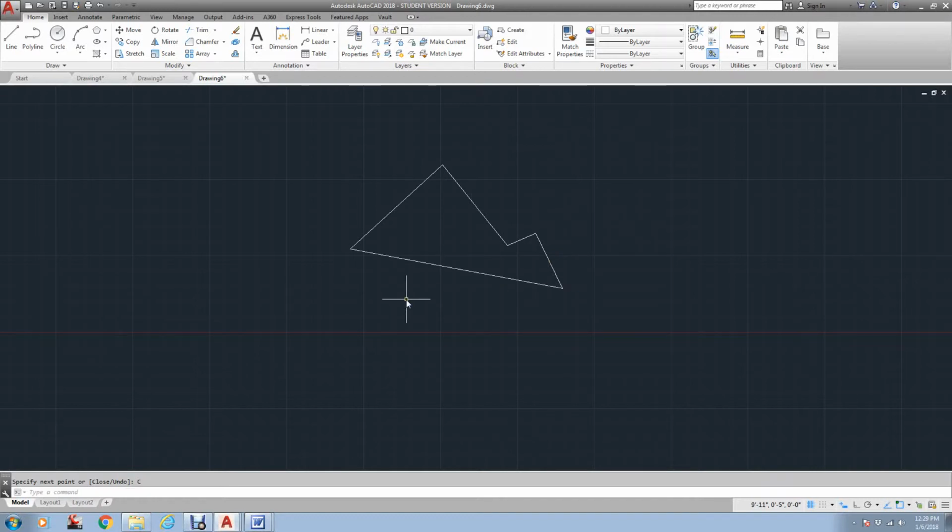Now, the one big thing with dynamic input is dealing with coordinates and polar input. I go into more specifics on that, but the big difference is knowing that down here, when you type in a coordinate, it is an absolute coordinate, whereas if you type it in up here, say 5 comma 5, let me start a line and go 5 comma 5.